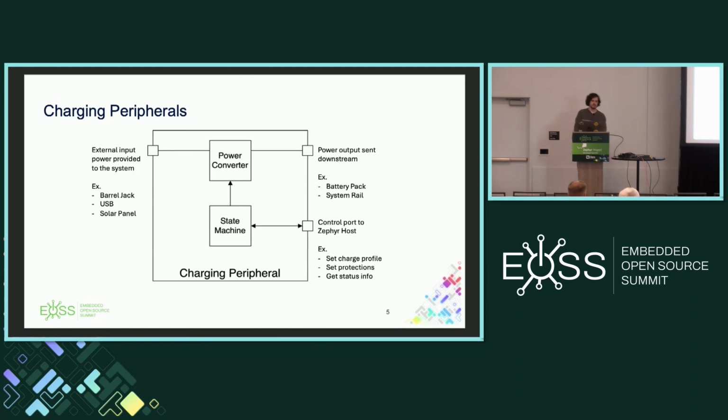These terms are, for the purposes of this presentation, interchangeable, but typically this will be an IC, so a dedicated charging chip, or it'll be integrated into a larger PMIC, so a power management IC. It could be a discrete circuit, but it typically isn't these days. And it looks like this. So colloquially, I know that a lot of people refer to the thing that you plug into mains into the wall as the charger, but again, this is the device that lives on board the end system,